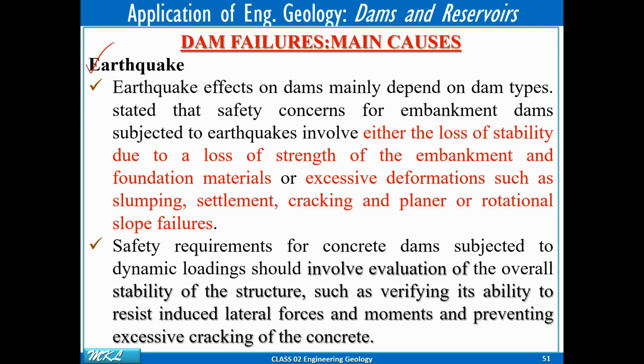Some liquefaction may happen underneath the dam. So slumping may happen, settlement may happen, or cracking and planar and rotational slope failure may happen. Due to these, earthquake is one of the primary causes of dam failure.